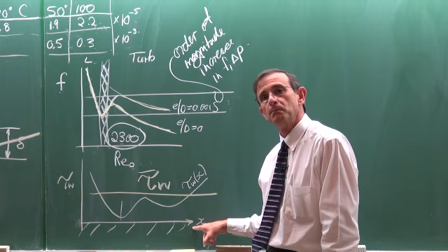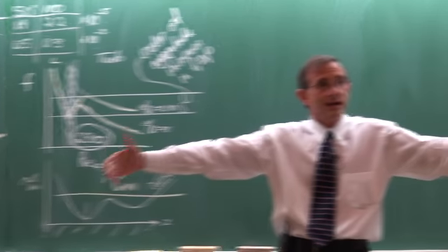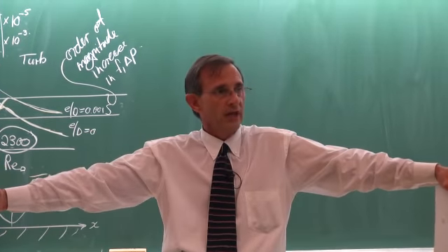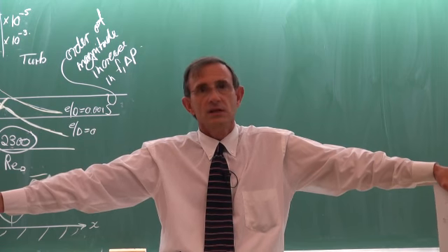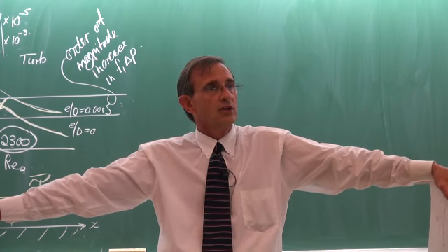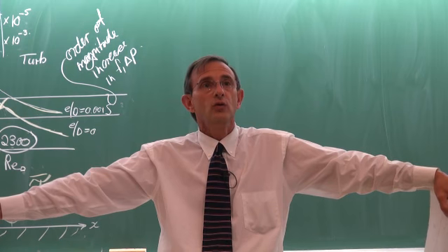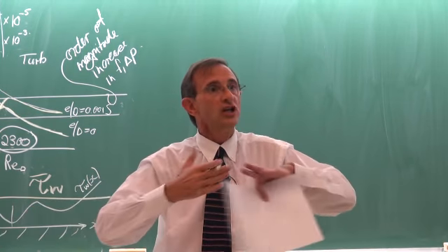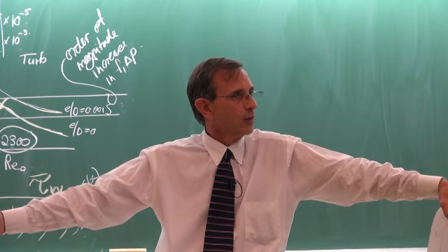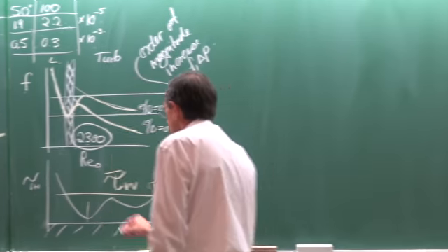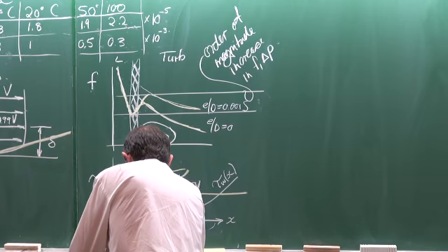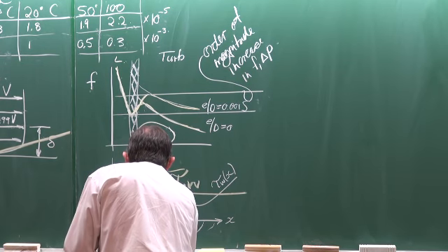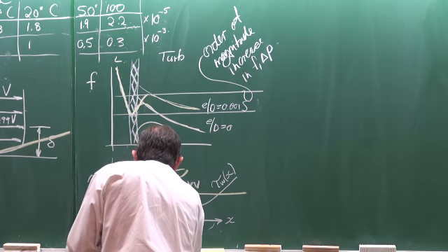If we have a flat plate or an aerofoil or the Airbus wing, there's no diameter. So the question is now, what do you choose in the selection of the characteristic length? Usually the chord of the aeroplane wing. So in this case, it would be approximately 300,000 to 600,000.